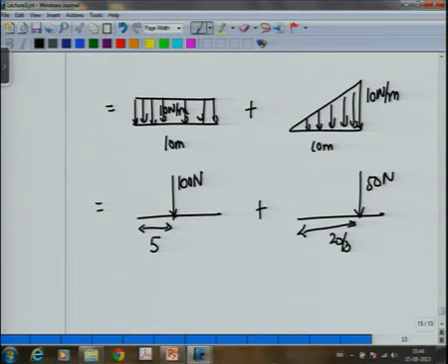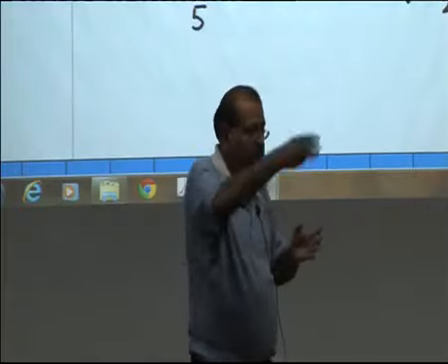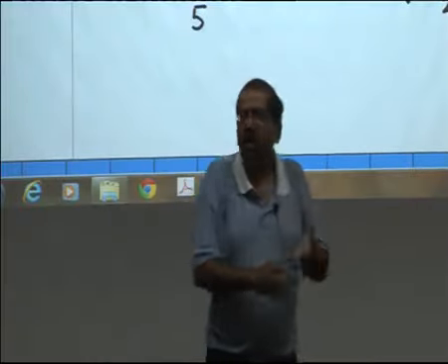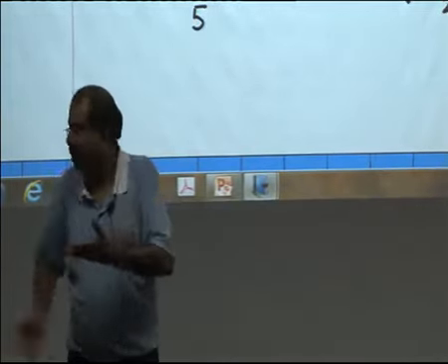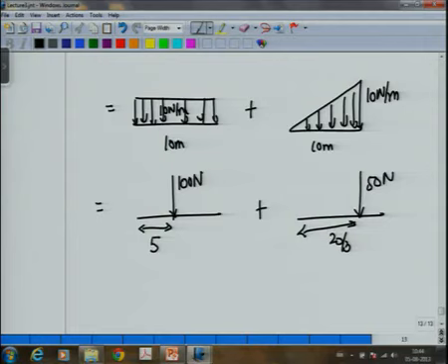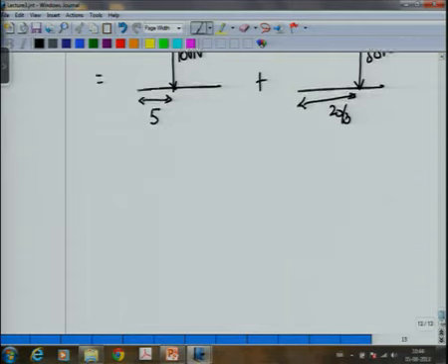Also, if there is a negative sign, then you will subtract things. So, you could have an upward force acting maybe in a reverse triangular way, then you just subtract because of that. So, this formula is an algebraic formula, you can add or subtract if there is a cutout, and this formula you must have used to find center of mass in a lot of cases, and in this problem also we will later on talk of center of gravity, and that is where we will use the composite formula again.